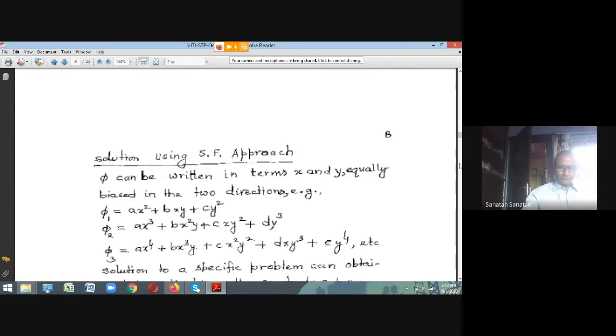Similarly, if you try to take the 4 times derivative of p x square y, c or x y square, it is going to be all 0. So therefore, it's satisfied. But then, when you try to take the stresses, you have to settle the constants a, b, c, d such that boundary stress conditions are satisfied. So this is another situation.